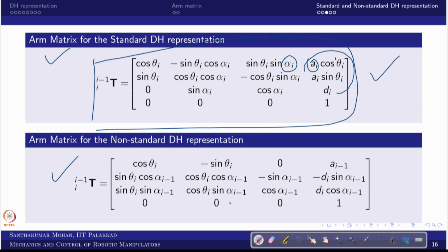So one should know this is what we have actually given. The other way around, people used to say, the non-standard is something like you are starting from the base to the end. The other way around is like you are standing at one particular joint. So you see the joint parameter with respect to the previous, and you see the link parameter with respect to you and what is preceding. In the sense you would be standing here and you call the information before and give the information to the front, but the non-standard one is slightly different. You will travel along the path. So that is why I favor this non-standard one.